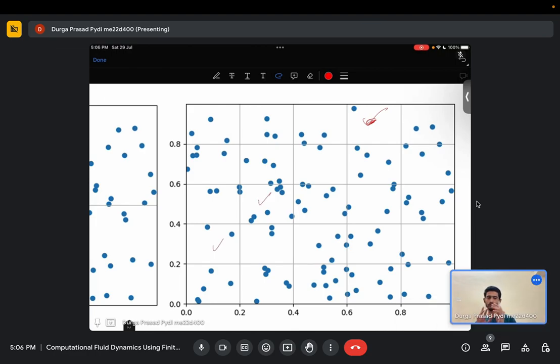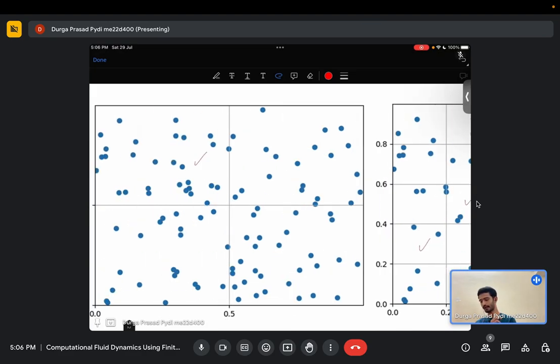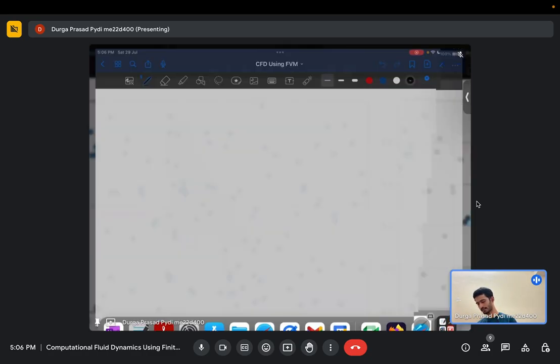So if you move across different spaces, you will have different values of densities. So only if the scale you have chosen is sufficiently larger will the values across different quadrants or different sections around which you are taking the average be equal, and then you will call that particular region valid for the continuum hypothesis. So that is how we define it, essentially from the concept of the Knudsen number.